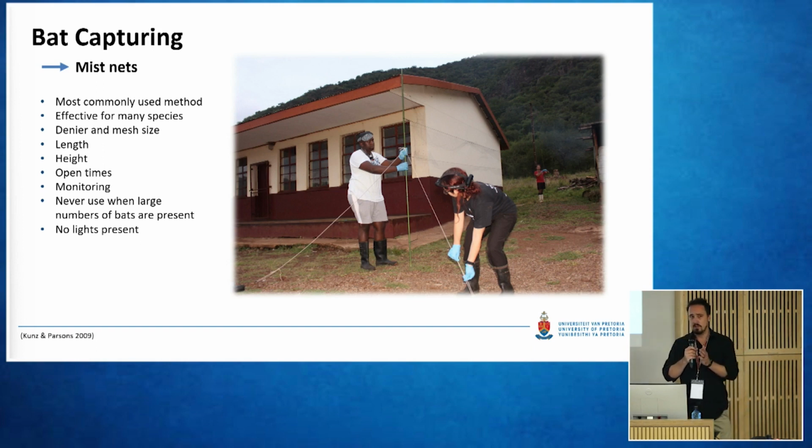It's always good to just have a few options available, so that when you get to a site where you don't know what to place, you actually have some options. If you're placing nets in a small gap, you've got the 3 meter available. If you're going across a river or something, you've got a 15 meter available. So you just have some room to play with. The heights of these nets are fairly standard, so it varies between 2.3 and 2.6 meters. But this you can vary as well. So I'm going to talk about stacking nets in that as well.